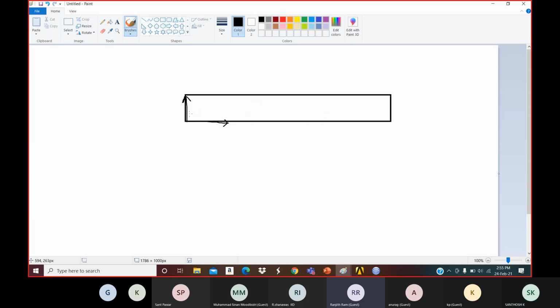Okay. No, sir, I don't want wall y plus. Fine, then you can undo that, not a problem. Our ultimate thing is I want to calculate the center line velocity, the skin friction coefficient and the outlet velocity. These 3 are the important parameters I have been calculating.